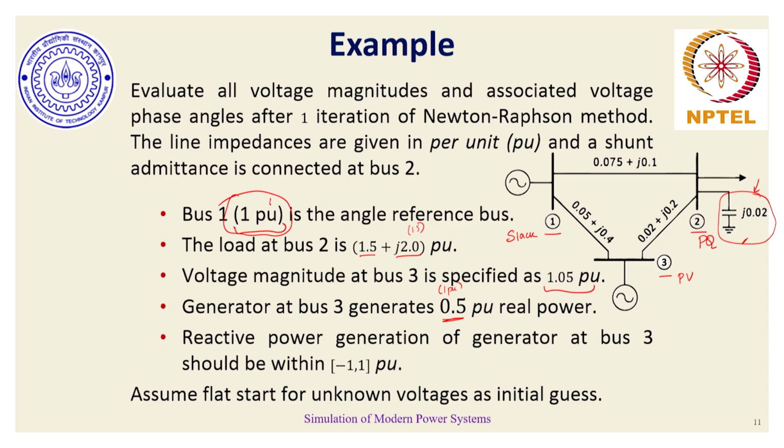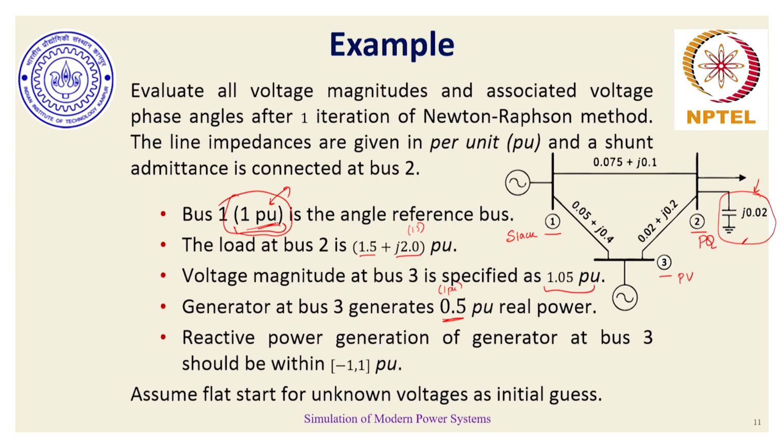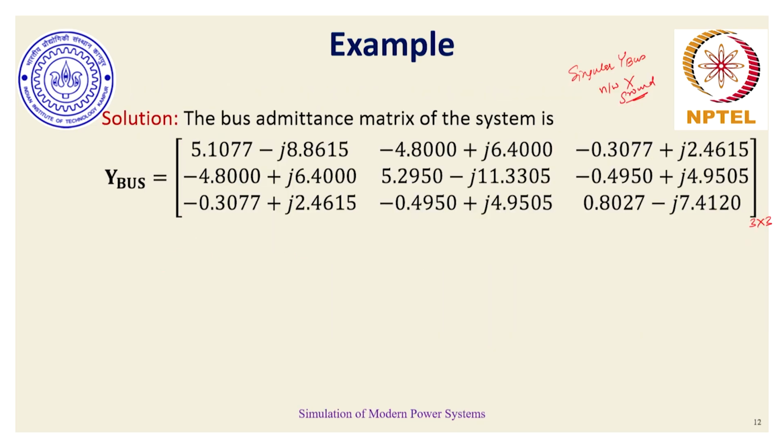And this specification of voltage magnitude lets power flow know what should be the mathematically correct voltage phasors at all of the buses. And hence, singularity of Y bus, which essentially indicates that the network is unconnected with ground, no matter the ground is unconnected, we are providing physical inputs in terms of voltage phasors, specifically magnitudes, which helps power flow converge to a solution. And that's the reason why power flow for Newton-Raphson polar version was working and converging to a solution.